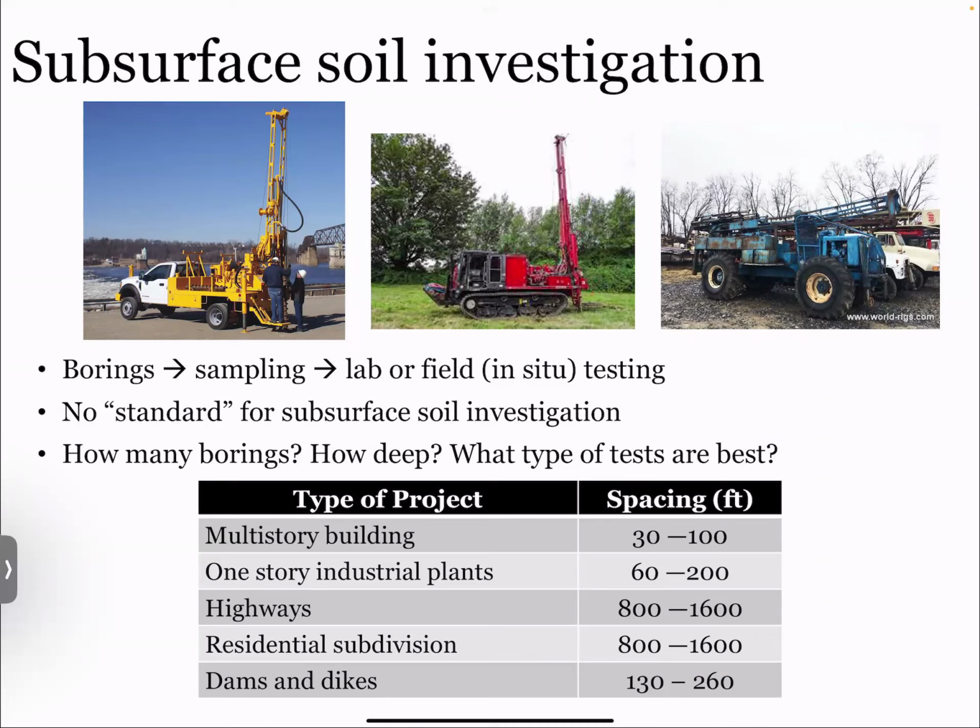The whole purpose of this is to drill into the ground. And part of that drilling is then to collect samples. And we'll talk about the different sampling techniques. But at the end of the day, what we want to do is get some ground truthing and say, okay, where is the clay layer? Where is the organic layer? Instead of generalizing, knowing where it is, in terms of elevation at this point, where do these layers exist? And can we collect soil samples to bring back to the lab?